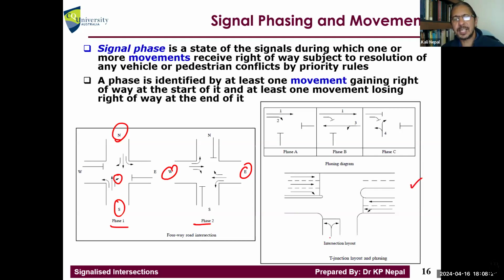In this example, because the south approach has only one lane, we need only one movement number, so that's movement 4. Vehicles going in the same direction need to be indicated at the same time as one movement. So let's say that's 2, that's 3, and that's 4. They are going through, so only 3, because both are going through. We cannot separate them out, right?